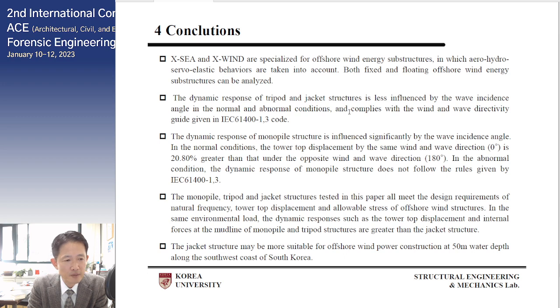But in the case of abnormal condition, the dynamic response of the monopile does not follow the rules given in the IEC code. The monopile, tripod and jacket structures tested in this paper all meet the design requirements of natural frequency, tower top displacement, and allowable stress on offshore wind energy substructures.